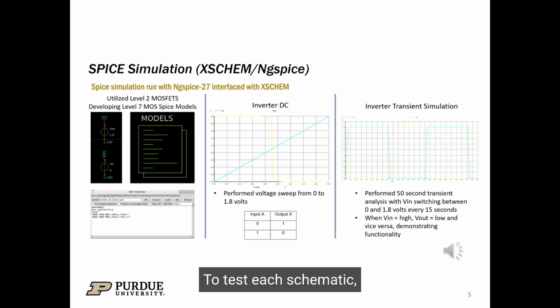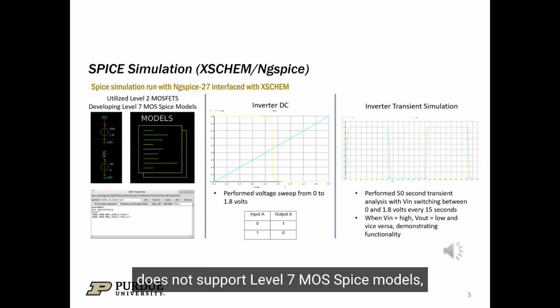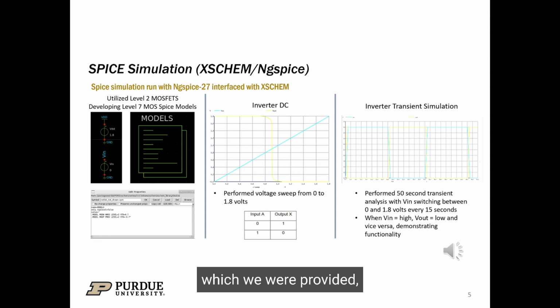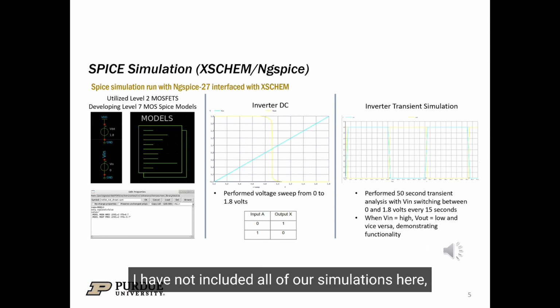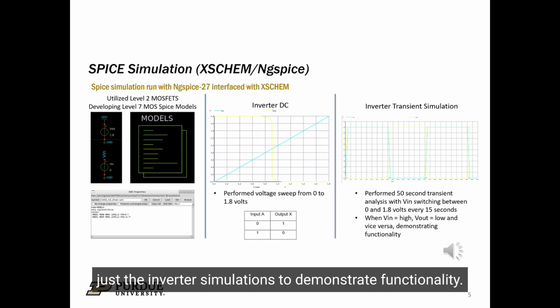To test each schematic, we ran simulations on XSchem using ngSpice as our simulator. For the simulations, because our current version of ngSpice does not support level 7 MOS spice models, which were provided, we are using MOS level 2 spice models for simulation. I have not included all of our simulations here, just the inverter simulations to demonstrate functionality.